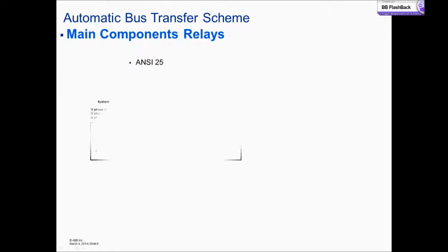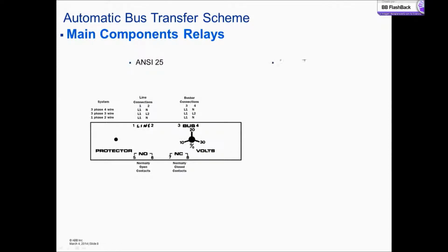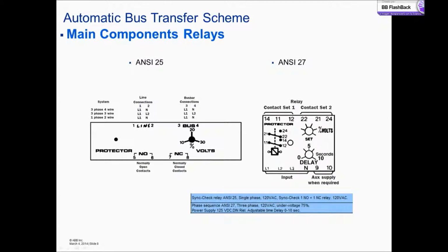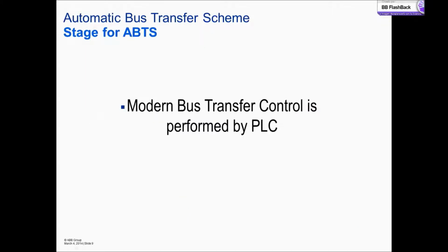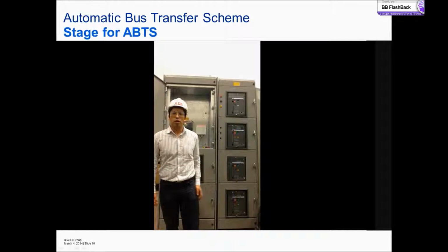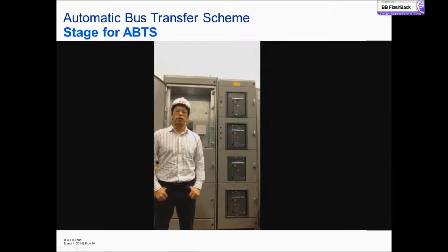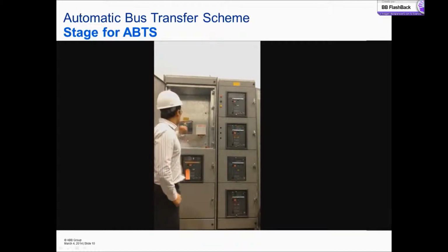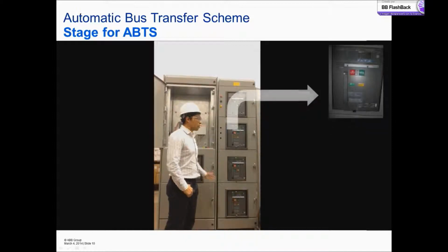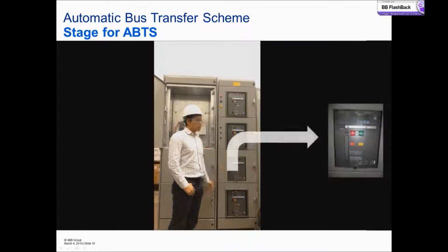We have 2 kinds of relays, one relay ANSI 25 and 2 relays ANSI 27. If we need more protection like ANSI 47, 50, 51, we can add it with wired logic. This project is shown by Carlos Ferretti, Application Engineering, and Daniel Martinez, Electrical Engineering, by R&D. This stage is with the MNS switchgear, resistant with 1 arc protection device like a TVOC2 and 3 IMAX circuit breakers with the main-tie-main configuration for the test.